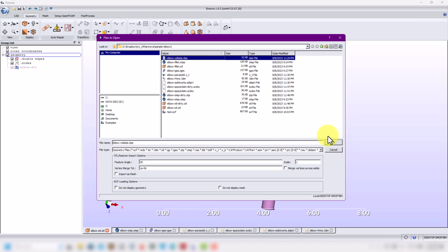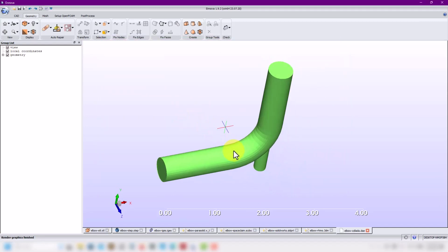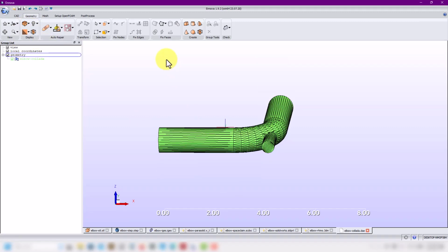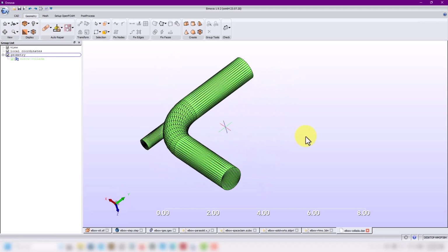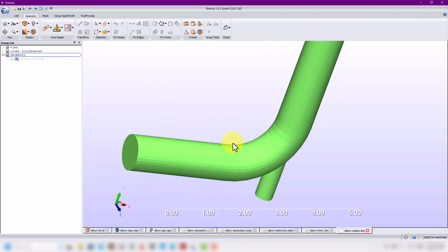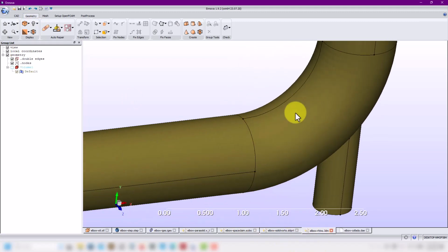And let me open this one just to show you the peculiarities about this format. So if I open, okay, and see that in this case, there is no edge information. It's just the triangulation. As you go here, triangulate, it will be similar to an STL file. So this is really bad in the sense that you don't have that information, what to follow the edges. Now remember that we're using a topology-based meshing tool.